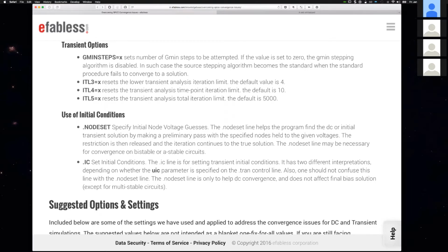And in the transient analysis, you can use the initial conditions. Usually in the transient analysis, you add UIC. There are examples of that in the manual. Once you enable that, it goes in combination with the .IC, which is the initial conditions node by node. If you leave it by default, it gets set to 0, and it puts the circuit in a different state, so that you can see the results, and it helps you either converge or get the right results.